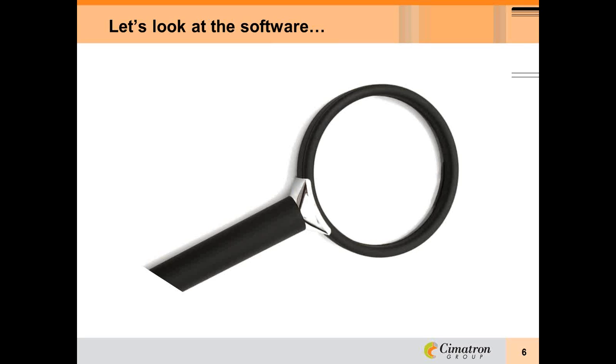Okay. Question is, can I modify a blank that the software has created before developing my strip layout? Yeah, sure. Obviously, Cimatron is going to take your part and make what it considers to be the blank, but we know that in design there are always areas where we have tolerance and we want to stay maybe safe. So you can always modify your blank before creating your strip. You can just simply add in offsets or different sizes as you see fit.